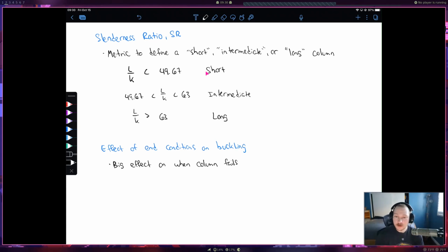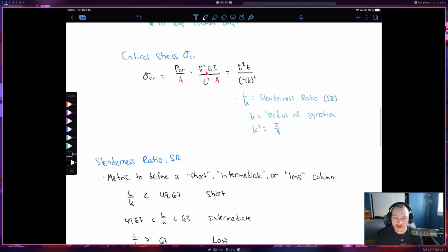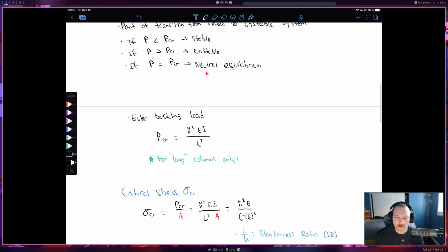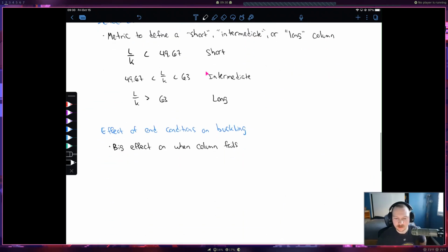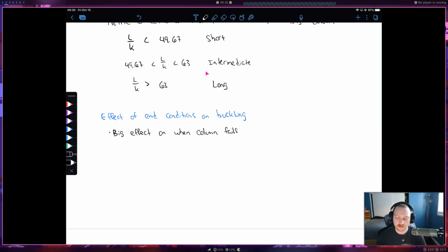Alright, so far, our theory, even though I haven't mentioned it, this Euler buckling load, was derived with the assumption that the end supports were pin-pin. But of course, that's not the case. We talked about how you can have fix-pin or pin-fix, or you can have fix-fix. So we've covered basically one aspect, but we can have those other two end supports as well.